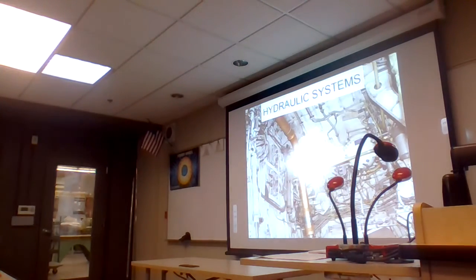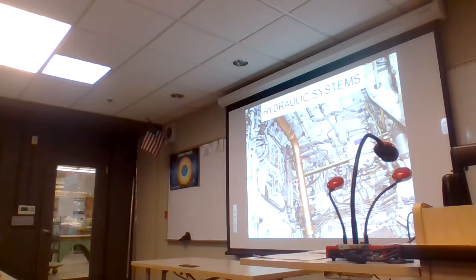And a little bit about hydraulic systems. It looks overwhelming when you look at a picture like this. This is the landing gear, the nose gear area, I think, of a 737. But you can see here, if you look closely, they've got color-coded tapes at different locations that indicate that they're generally hydraulic. In addition, you'll see a lot of purple tags in aircraft near hydraulic components. That tells me something special too. It gives me a clue as to the type of hydraulic fluid that might be used. It's probably going to be a phosphate ester-based fluid, like Skydrol.